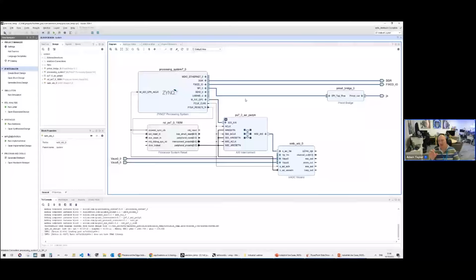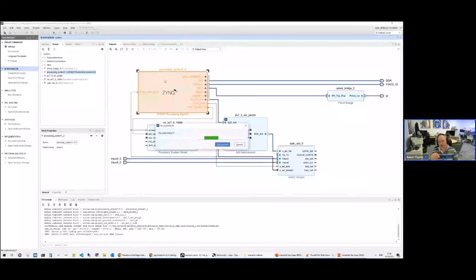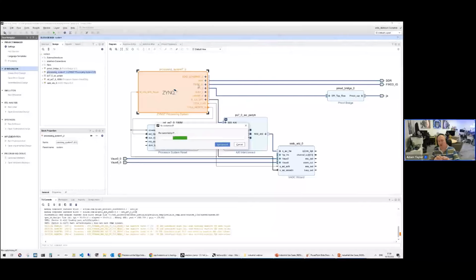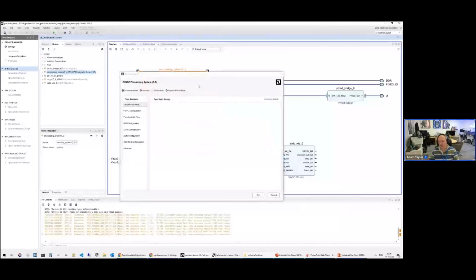And then what we've done, because there's no IP core to drive the PMOD DA4, but it's just a SPI type interface, so we've used the PMOD bridge IP from the Digilent IP core library. We've also configured the Zynq processing system to make the SPI external and available over what's called the extended EMIO. So it's not going out over the PS MIO. It gives the SPI access to the programmable logic IO, and we've routed it then to the necessary PMOD port on the FPGA.